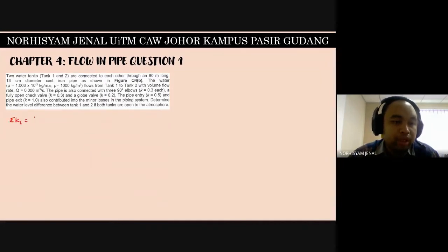So summation of KL is, number one, we have here given to you 3 90-degree elbow. So 3 times 0.3 plus a fully open check valve.